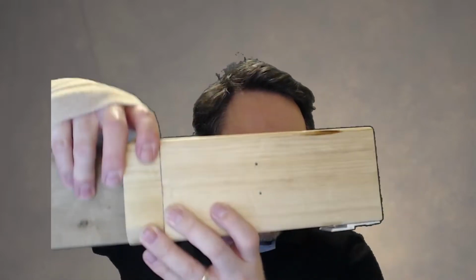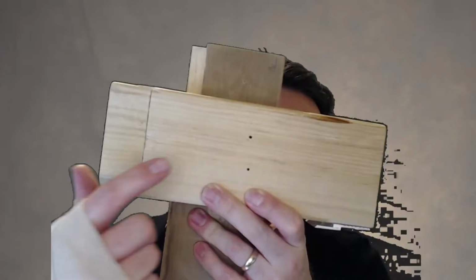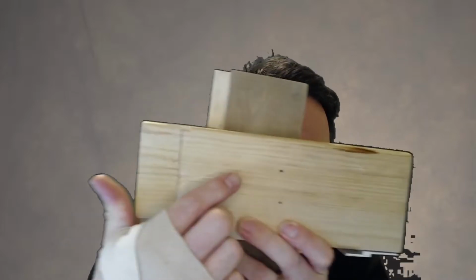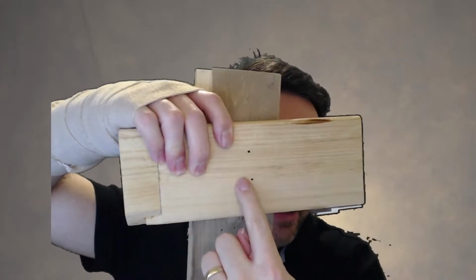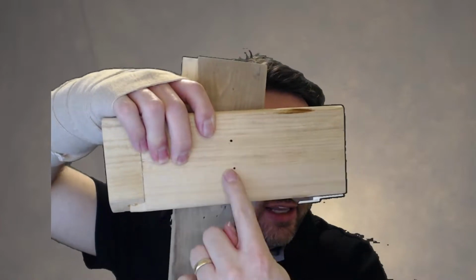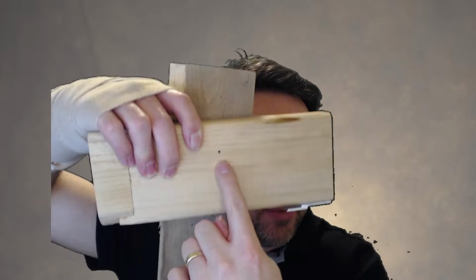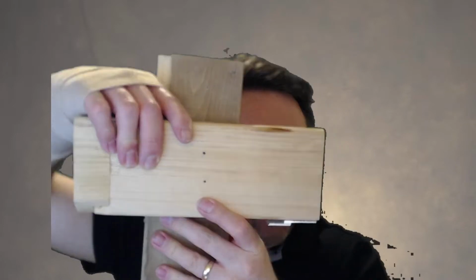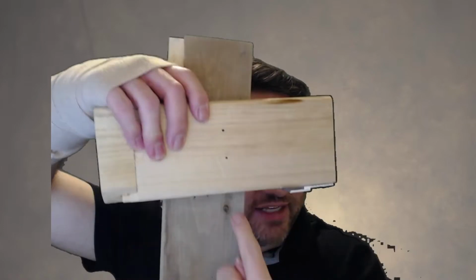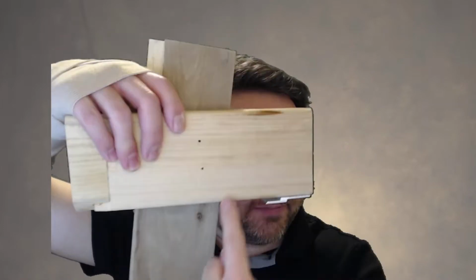Now, if I twist one of those pieces of wood like this, the grain directions do not align anymore. So that means that if I put two nails in these two holes that are already here, this hole and this hole, then in this direction here they are perpendicular to grain. So that's a perpendicular to grain distance that I have to check. But in the other piece of wood behind, that direction is the longitudinal, parallel to grain direction.